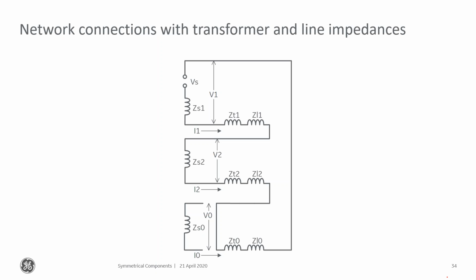My metering location is right here and here and here. At that relay, I can calculate zero sequence current, negative sequence current, and positive sequence current. At that meter location, for a ground fault downstream of that device, those negative, positive, and zero sequence quantities should be the same magnitude. My negative sequence voltage is going to be a little bit different. My zero sequence is similar.